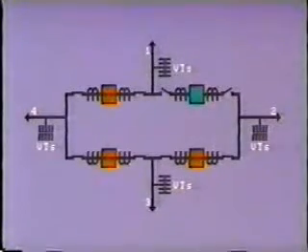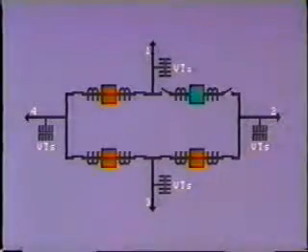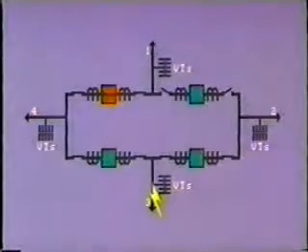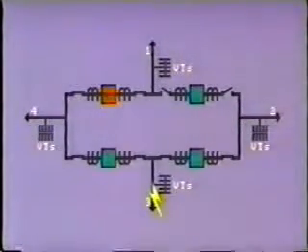If a circuit breaker is removed for maintenance, the bus still remains connected to the 4 circuits, but it is now an open bus. However, in this situation, if a fault occurs on one line, then the bus will be split as additional breakers open.